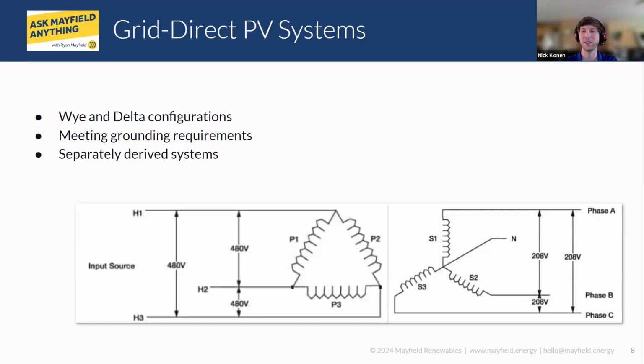Honestly, I don't have the greatest answer on that one. I'm more of the guy who picks these single lines. But I do see a common preference, usually in certain geographical locations, for the utility Y. If anything, it can cause problems again with the neutral flux coming back through the neutral of our transformer. But I could see it in battery storage type applications where, without the presence of the utility, you do need something to establish a neutral on the grid side.